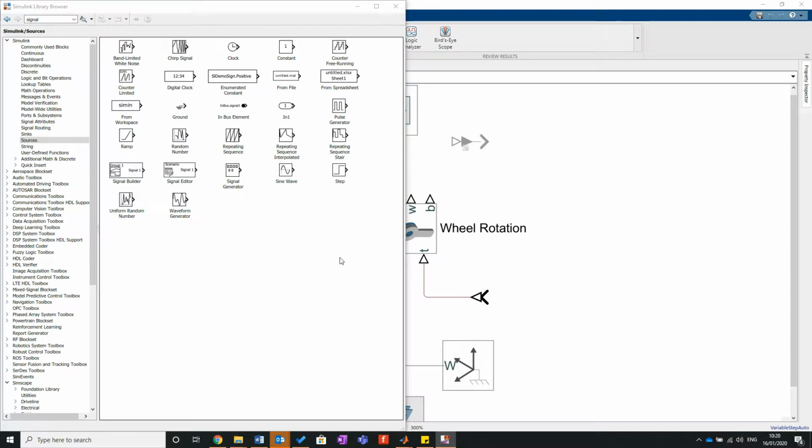It's really useful. But for me, the signal builder, I do really like it as a first initial input. If you get very sophisticated and you get real live data acquisition, see the from mat file, you can actually bring in a data stream that way. You can actually read from a spreadsheet directly. You can do anything that you want with it. Read from spreadsheets are phenomenal for gravity, because it will read a particular time step and actually change things, or if you have a variable damping system, if you have a non-linear response of something, phenomenal. Anyway, let's get back to the actual example.